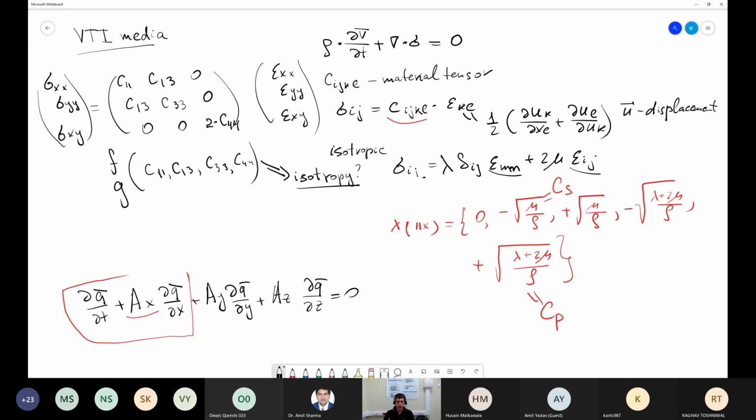And in this case, we will obtain 3 different eigenvalues, different by modulus. So we will obtain 3 different waves propagating inside the porous medium: the wave inside the fluid, the wave inside the skeleton, and a wave due to the interchange of the pulse between the acoustic fluid in pores and the elastic skeleton. And I will show you the code that I prepared for you and comment briefly on this code. And we will stop our lecture at this point.